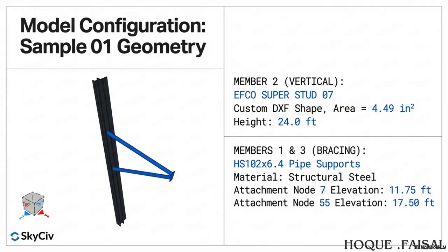Right. There's a screenshot in the document, SM102.jpg. It shows the bending forces on that main 24-foot beam. It looks like a snake. It curves one way, then it crosses the center line, curves the other way, then crosses back again. That S-curve, that snake shape, is the unmistakable fingerprint of a fixed connection. It physically shows the ends of the beam grabbing it and twisting it back against the wind.